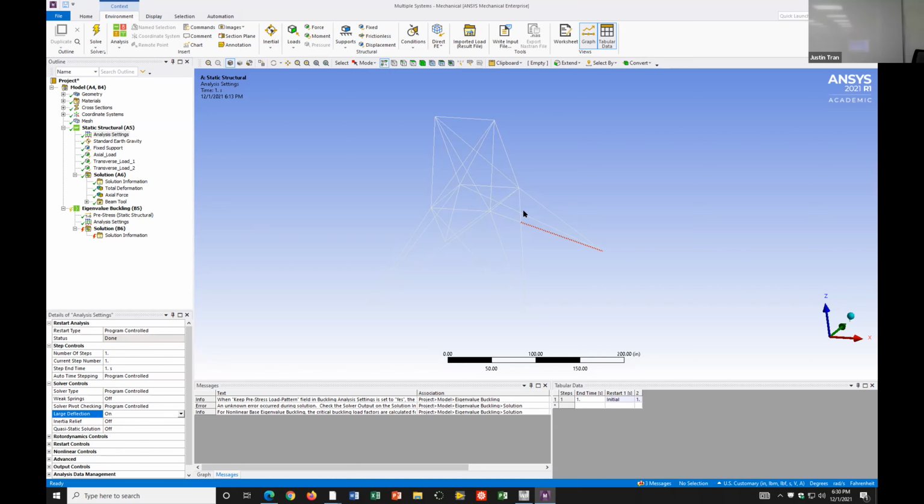And you're actually seeing a little bit of buckling here. You can see over here, the graph mostly follows one slope, and then right here you can see it's starting to uptick, right? So this is probably where buckling occurs. If you look at your mode multipliers, it's probably somewhere in the ballpark of 0.6, 0.7. Exactly, and you're seeing that right there. So the first sign of buckling is when that graph goes from one slope to another slope.